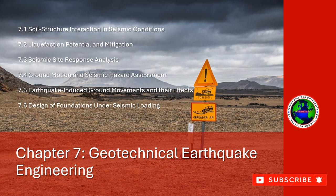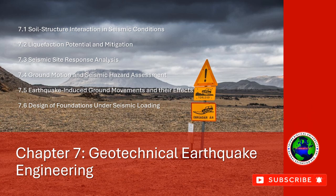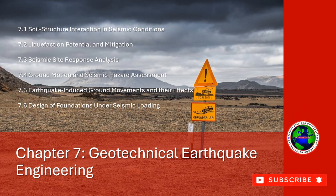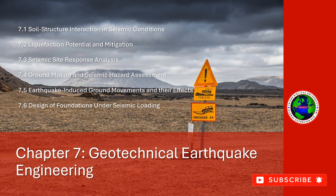5. Zoning and land use planning. Avoiding construction on or near active fault zones, liquefaction-prone areas, or steep slopes can significantly reduce the risk of damage from earthquake-induced ground movements. Zoning laws and building codes should reflect seismic risk assessments and include provisions for reinforcing structures in high-risk areas.